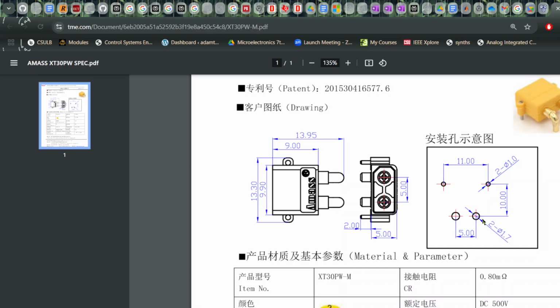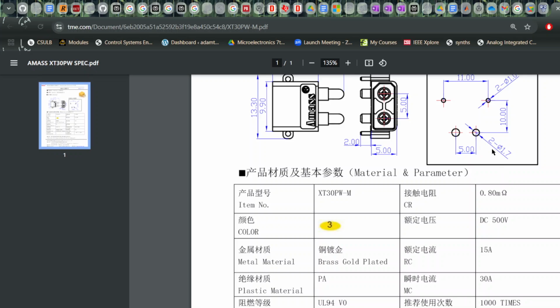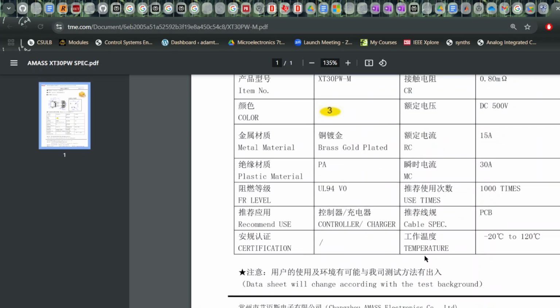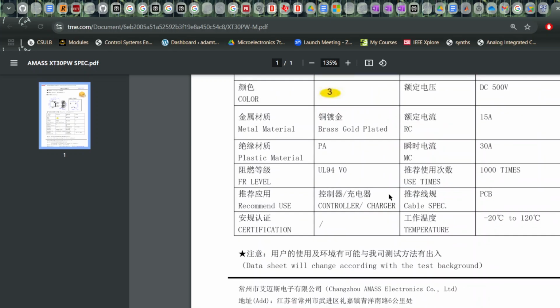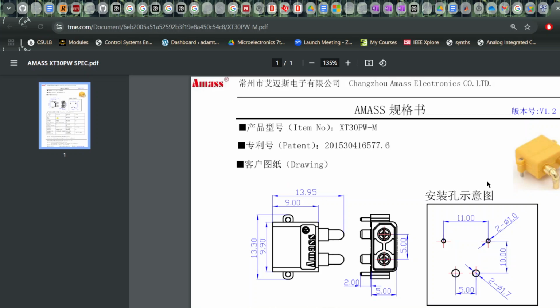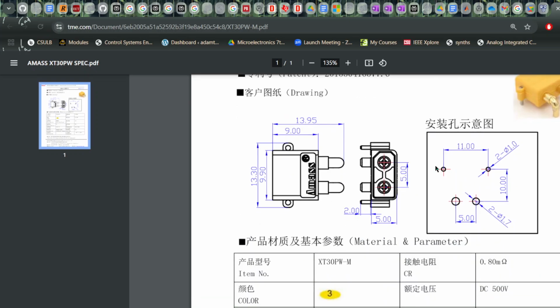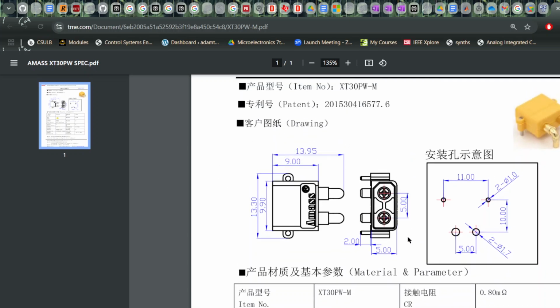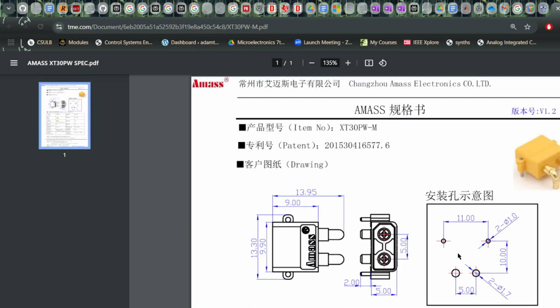But before we place any of the other ones, we need to match the hole size. The hole size for these ones, it looks like, is 1.7, and for the units, most of these are going to be in millimeters. It might say it here and I just can't read it, but I'd assume that the units for all of these are in millimeters, unless otherwise stated. So the hole for this is going to be those two arrows pointing into it. So it's going to be 1.7.